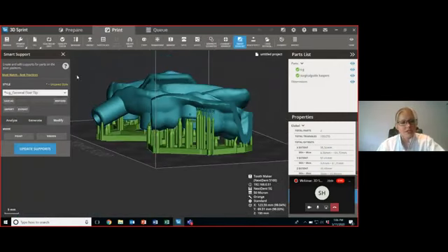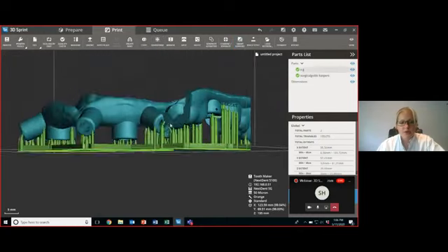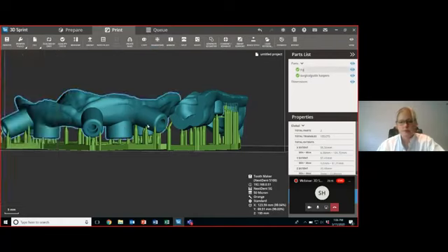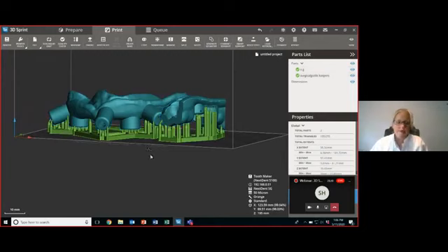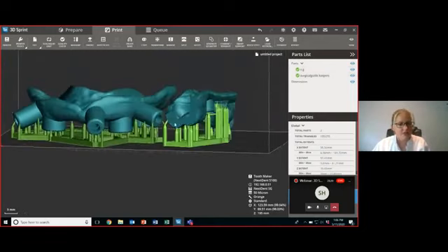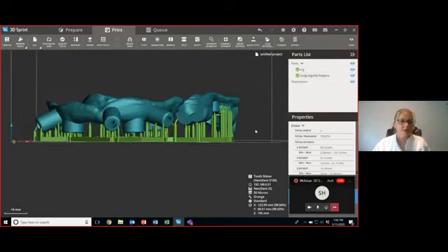So one of the last functions that I wanted to show you in Transform is that even if you want to move these around a little bit, you can actually keep your supports now. It used to be where you had to regenerate your supports. So that's the new support style and how to change that over. Now you still can keep using the thick one. If you do, you may have more adjustments to make. So I would encourage you to start transferring over to that fine tip support.